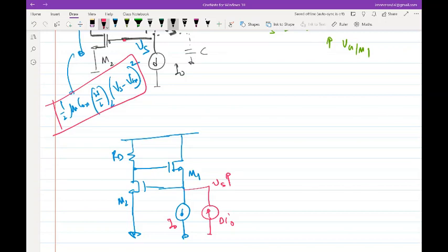Yes, but by how much? No, right? Why? So what is the relationship between these two nodes? Exactly, right? It will be exactly that. So the rate of change of VG and VS are related by what? This is the gain stage. This is the common source stage. Gm2 times RD, isn't it?